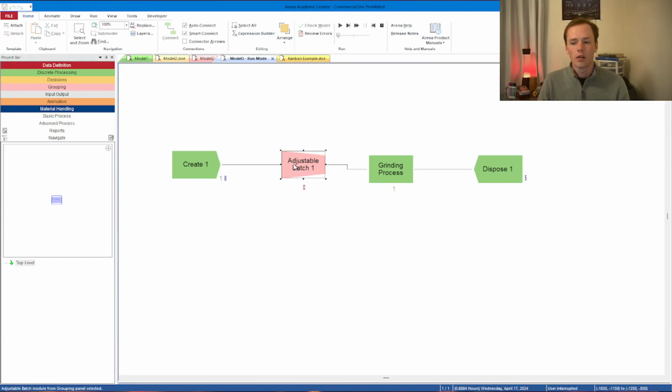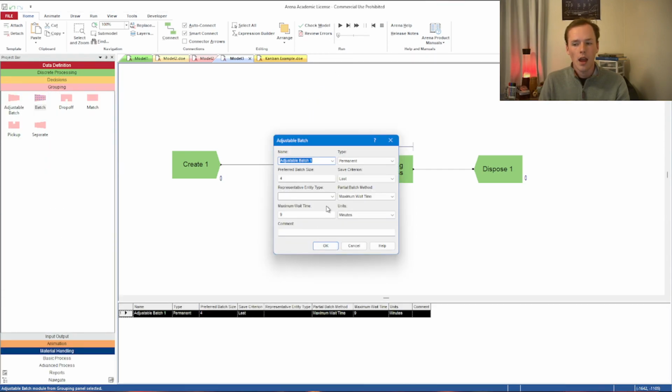At the very end, whenever you are combining something, I would make sure that you set it to be a representative entity type, a new name for your entity. If you have it as the old one, you're going to start counting 3 times as high as you probably should if you're batching 3 times together. So every time I batch, I just name something else, because as far as I understand it, when 2 things come into the process, it's going to turn both of those things into a new entity, especially if you have a save type of permanent on there.